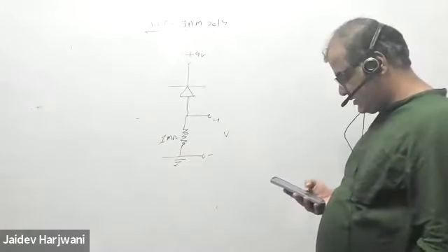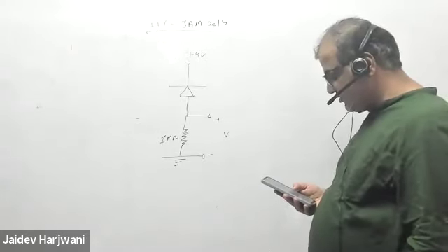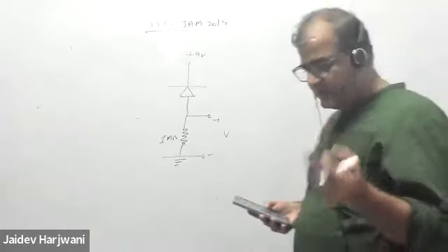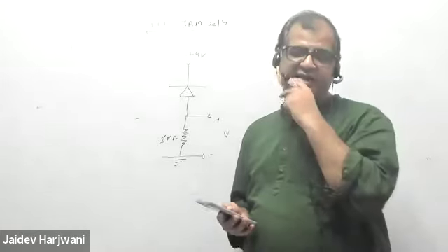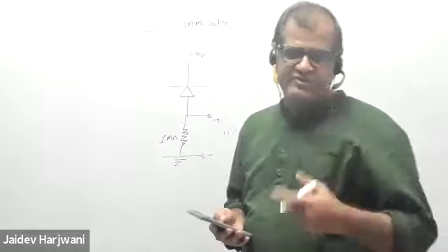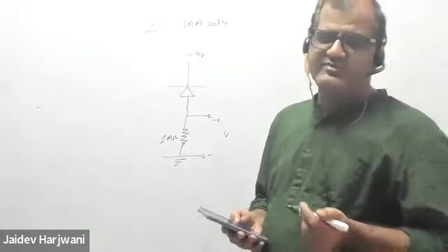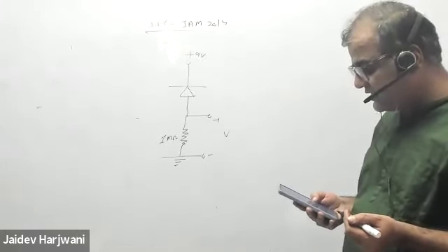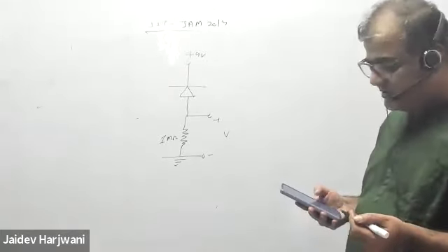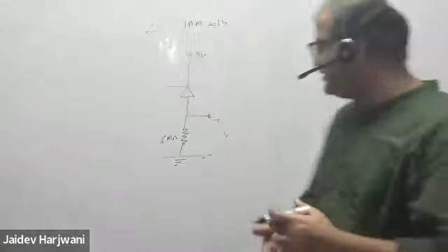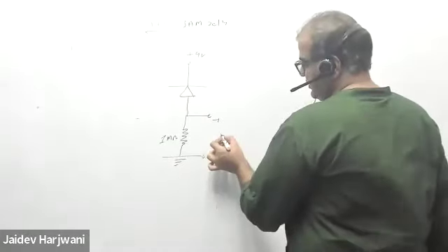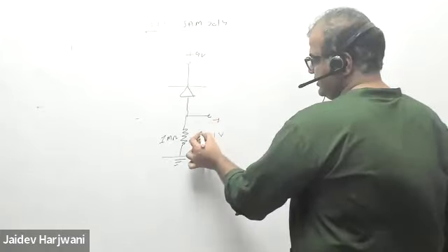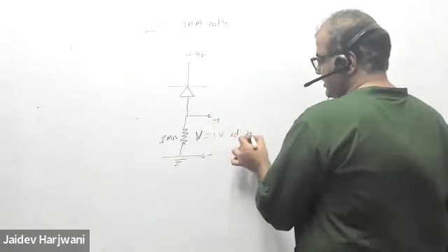Okay, and if V were equal to 1 volt, but this current is always dependent on temperature, and it becomes twice every 10 degrees centigrade increase. In general, any reverse saturation current doubles for an increase of temperature of 10 degrees centigrade. Okay, so the question is saying, if V is equal to 1 volt at 20 degrees centigrade, find the value of V at 40 degrees centigrade. So you have been given the value of V equal to 1 volt here, okay, at 20 degrees centigrade.